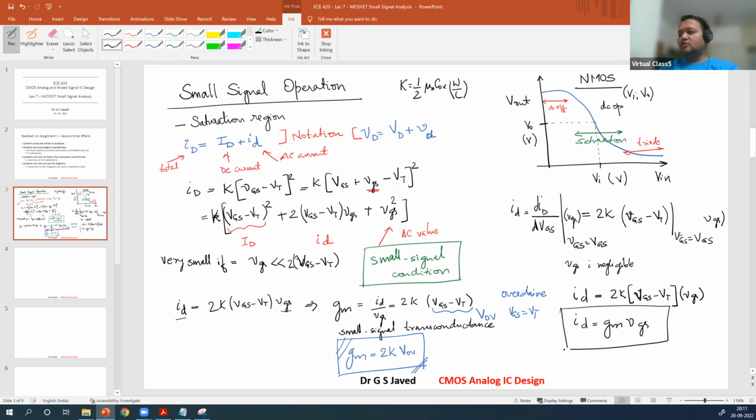This is also going to be a common equation that you will use in small signal analysis, which is the current topic that we are going to look ahead. So, current is equal to transconductance multiplied by the differential voltage across it.